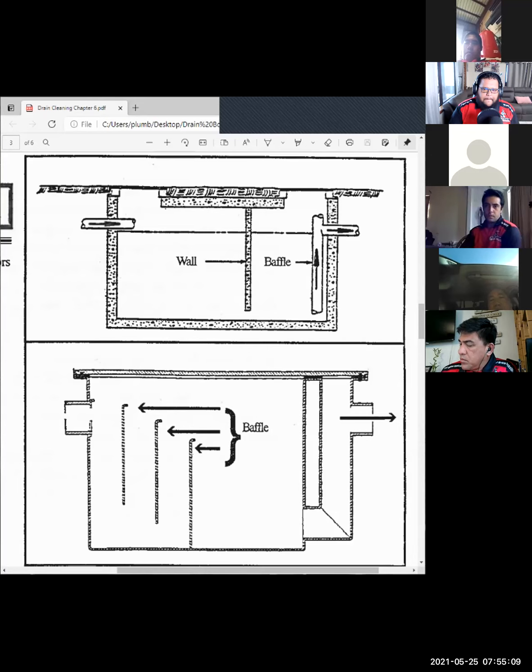You say, hey, listen, the diagnostic would be being able to look down that vertical section on that baffle and see water coming in. So you're clear upstream, right? Water's flowing into the interceptor. But you have to have the ability to diagnose properly. And if the interceptor's failed, I have seen many interceptors where that T's fallen off. It's not connected. Well, that's a correction. Anytime you see something in there that you can't diagnose, and you understand how it's supposed to look, then it needs to be corrected.